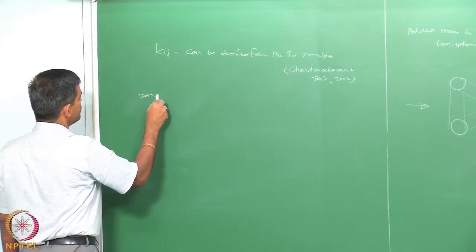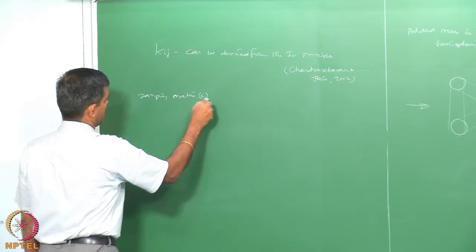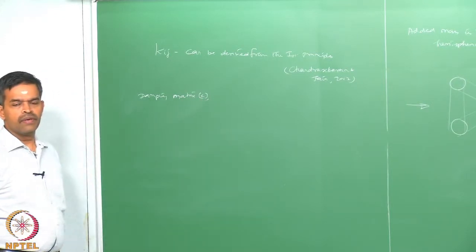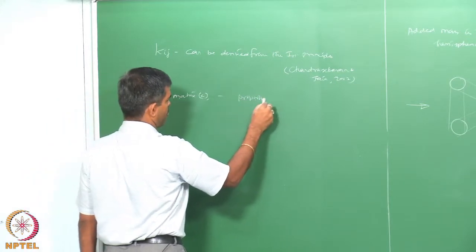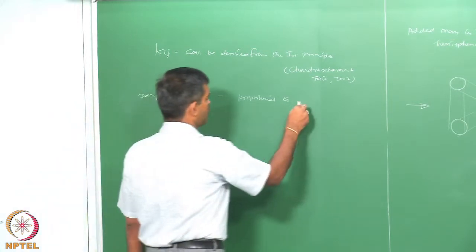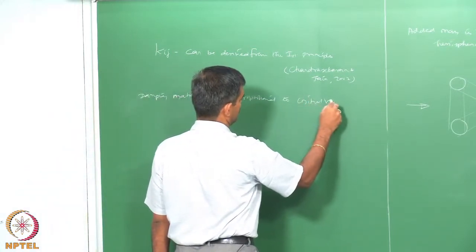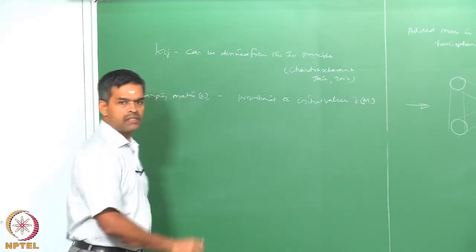Damping matrix C in this case is assumed to be proportional to initial values of mass matrix and stiffness matrix.